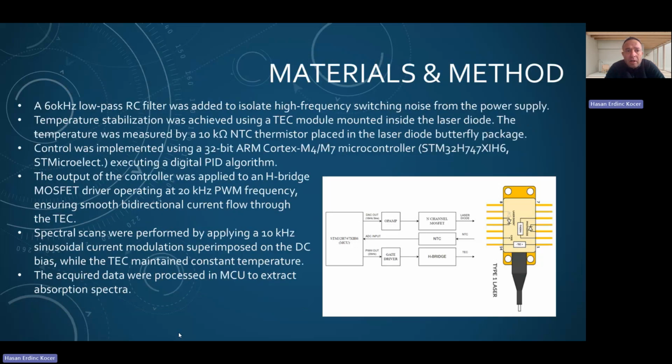Also, a 60 kilohertz low pass RC filter was used in this system to isolate high frequency switching noise from the power supply.